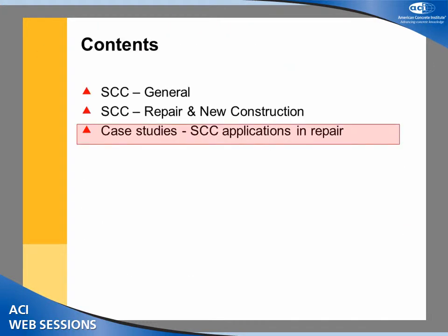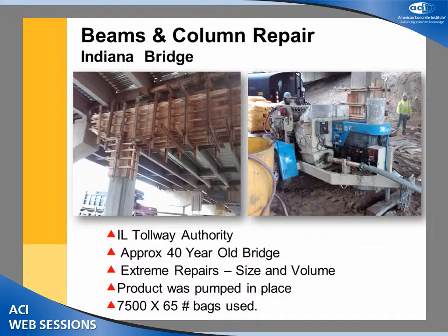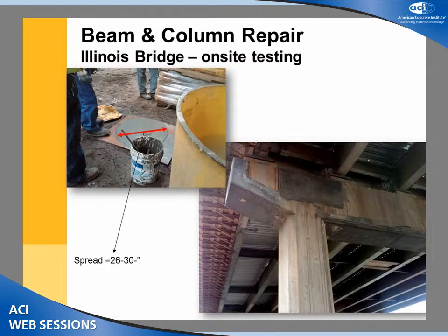Now let's get into the SCC applications and repair. This is a project in Indiana. It's a bridge structure. The owner on this project is Illinois Tollway Authority. It's an approximately 40-year-old bridge. Extreme repairs from a size and volume perspective. On this project, the SCC prepackaged material was actually pumped into place, and a lot of material was used with a lot of success. This was a smart contractor who was testing the slump on site, making sure that what he's putting in the forms is actually meeting the spec. And if you take all the precautions, you do get a good repair in the end.